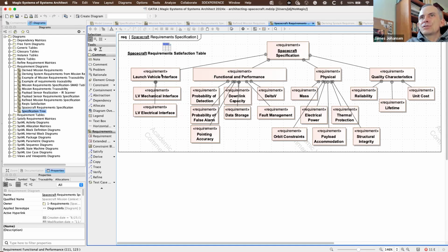We have some larger sub areas. How much weight am I going to allocate here? What is the electric power? This is the thing that Kyle would want to focus on. What are the payload accommodations? How large of an interface is that payload going to have? If you think of a CubeSat, is it going to have one board in a 1U CubeSat? That might fall out into that. The spacecraft would also have general characteristics, like how long it is going to last. For this example, we talked about 8 years being the goal. That's just a couple of examples.